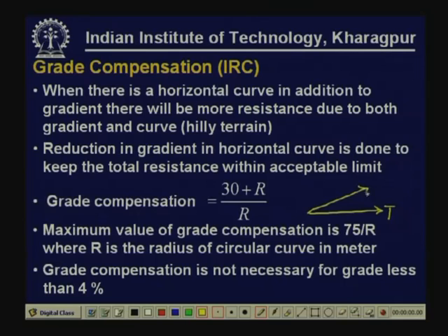Then only the T cos alpha component, if this angle is alpha, is available in the direction of movement, because the tractive force T is at the rear axle, and the front wheels are rotated in this direction, making an angle alpha. So, therefore, in the direction of movement, T cos alpha is available.